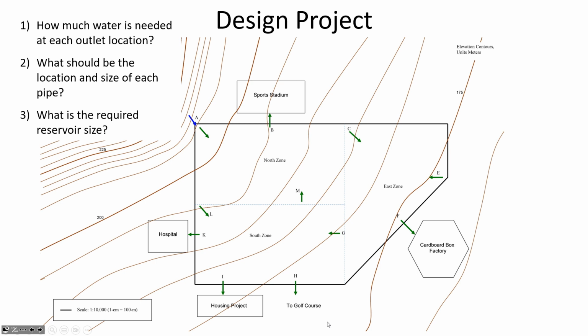They know the volume of water that's required, and then they say, well, there's 24 hours in a day, so just divide the volume that's needed by how many seconds are in a day. But they don't think, well, you can't leave the water going when people are golfing, right? The water can only occur in a smaller period than 24 hours per day. So I'll give you feedback on the demand estimation, hopefully early enough that you can incorporate that into the pipe sizing.